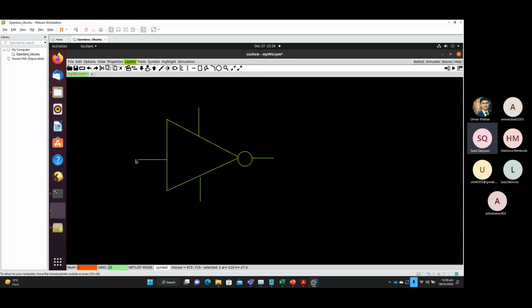Generally, it's better to place the pins first, because I've increased the grid. Okay, it was better that I put 4 pins first, and now I'm messing this up a bit. No, at 2.5 it would cause problems in the schematic. There it is generally bigger. So it's better to start with the pins first. So you add 4 pins and then create the symbol around them.